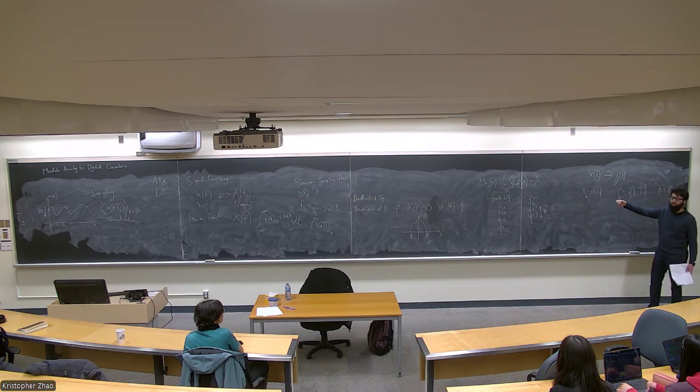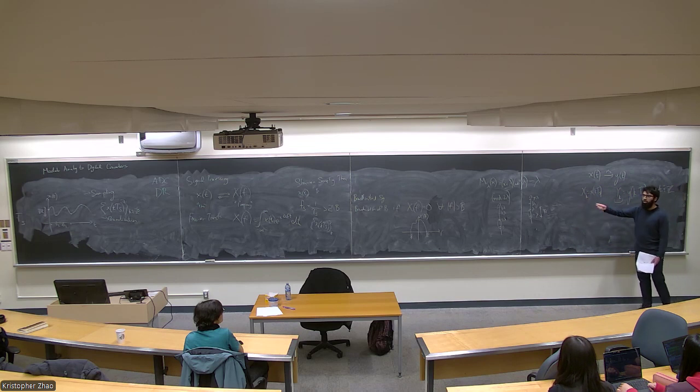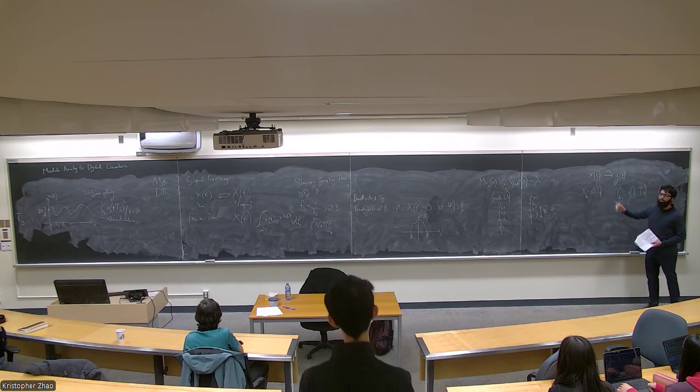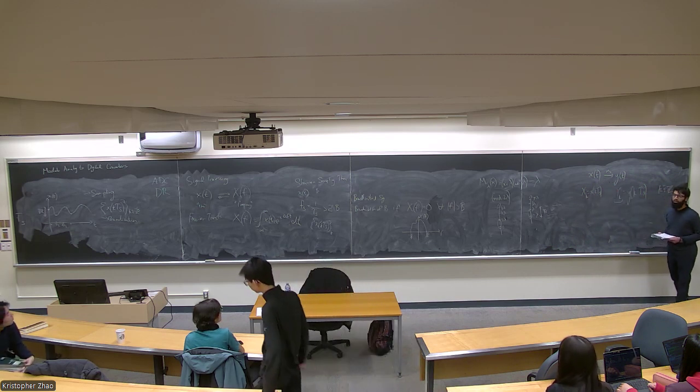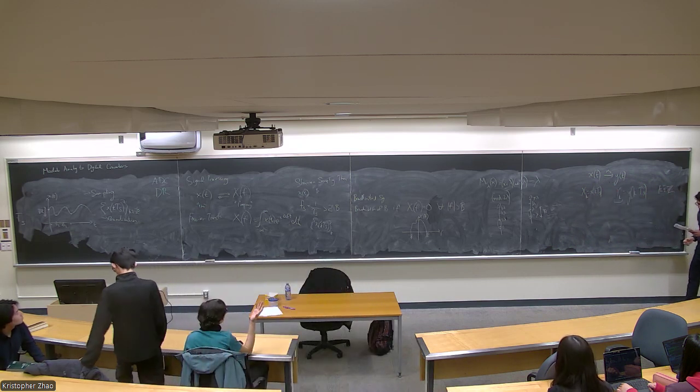as we know from the Shannon sampling theorem, if we have these x sub k and we meet the criterion on the value of Ts, then we're able to go from x sub k back to x of t. So our overall goal in this problem is to go from y sub k to x sub k, and from there recover your overall input, which was a continuous time signal.